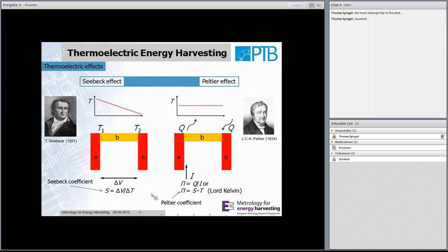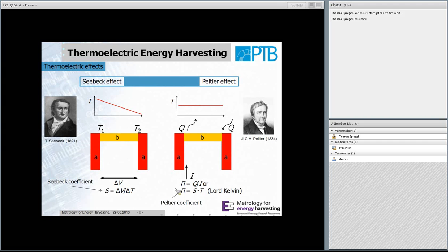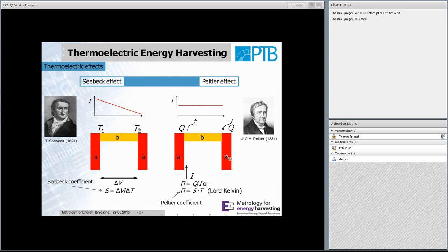And the other junction, when they transfer from the material where they transport lower energy to the material A where they transport higher energy, they take this difference of the energy from the lattice, and this junction cools down. The heat absorbed or created is directly proportional to the current which is flowing, and you can see the Peltier coefficient is the ratio of heat divided by current.